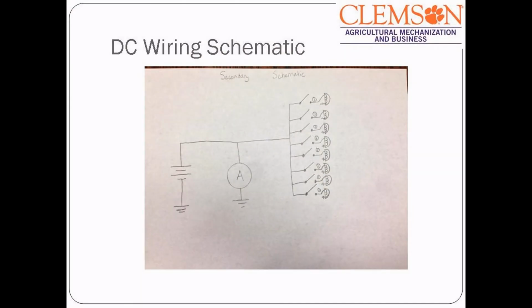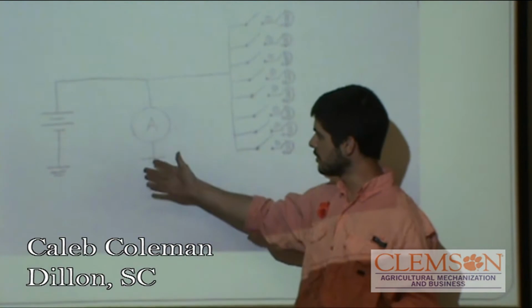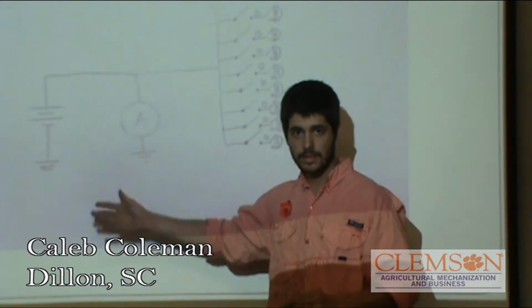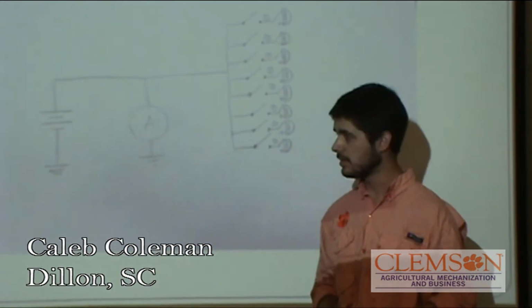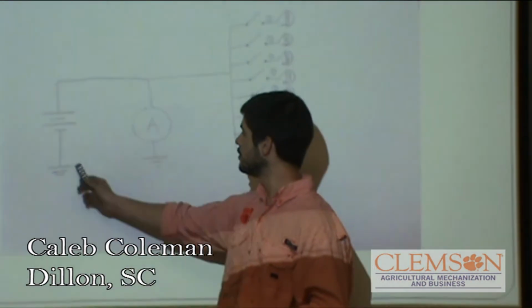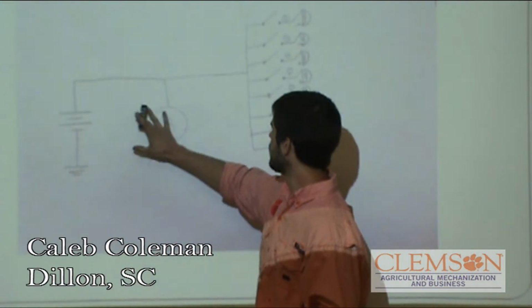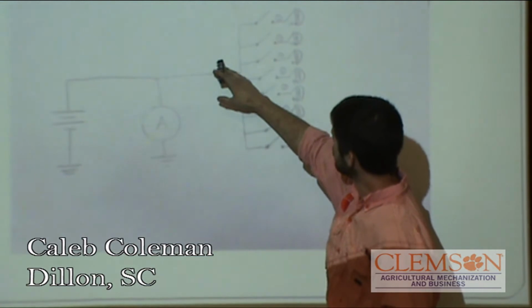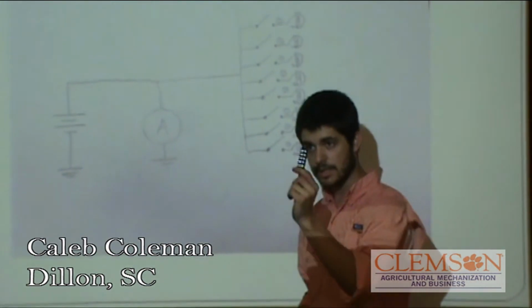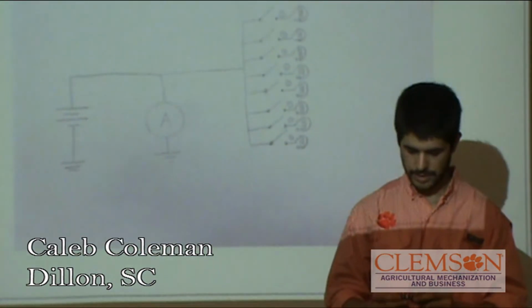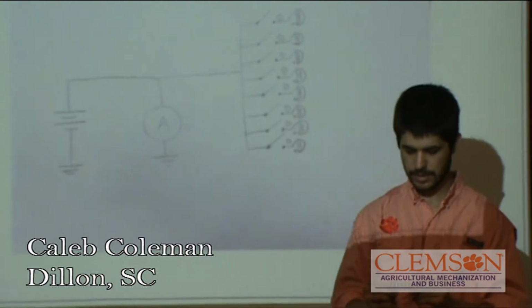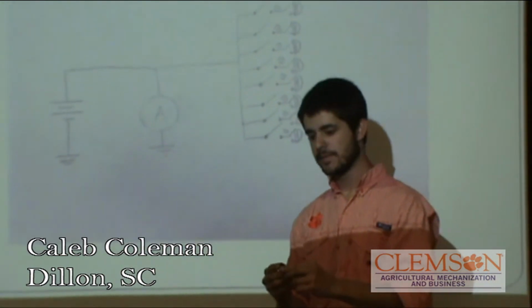And here's our DC wire schematic. We've explained it before, just want to bring it up again to show what we used for right here. We initially wanted to use 8-gauge here. We found out we were going to be pushing way too much energy through it, so we went down to 2-gauge from our battery and our alternator, and to feed into this one central point to come into 8, we took a little bank here, and Kendall drew us up a blueprint, and we cut out a piece of aluminum.